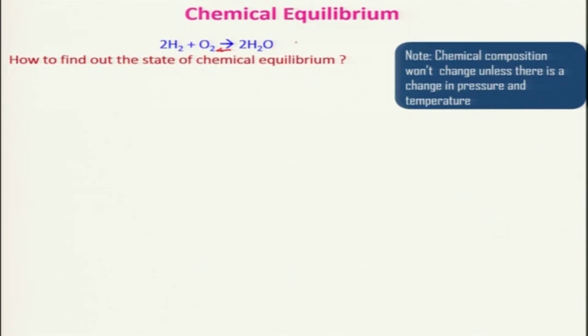It can be H2 hydrogen, and the product can also contain oxygen, it can contain OH, it can contain H, it can contain several other things as well. So, all these constituents should be known properly to find out the adiabatic temperature, and unless you know the adiabatic temperature, you do not really know the combustion product.